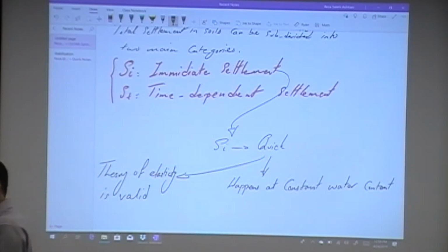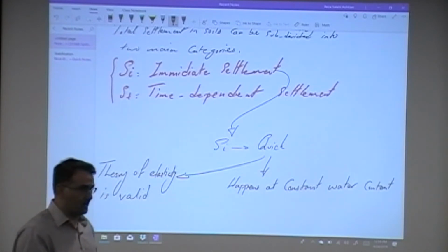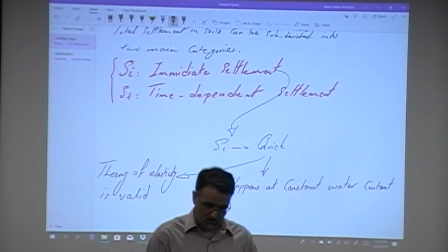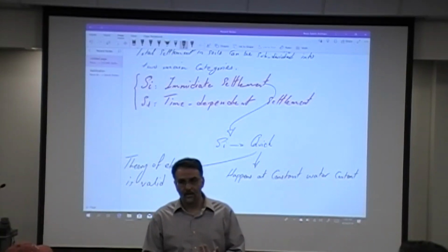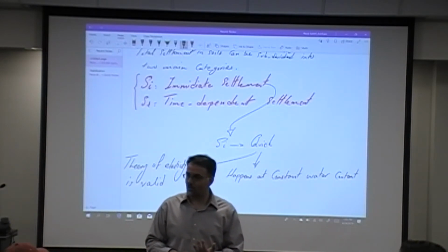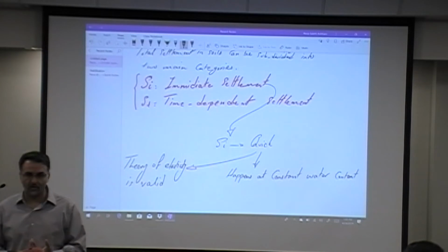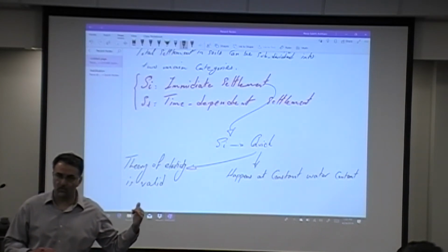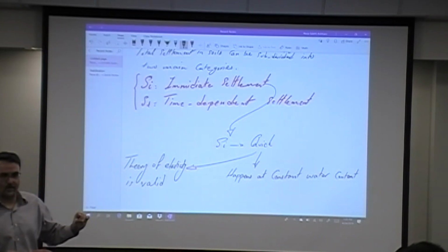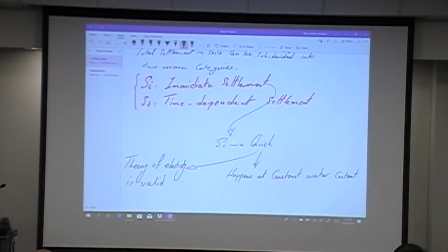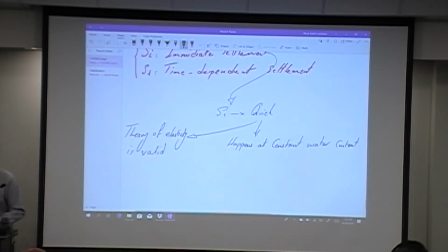Now, if you want to characterize that material, you need two parameters, or two material properties. Those are Poisson ratio and elastic modulus, right? So you need two material properties, elastic modulus and Poisson ratio, to be able to calculate the deformation associated with the elastic deformations, right? So that's basically what we have in terms of the calculations. So let's quickly talk about how you can do the calculations here. It's very simple and straightforward.